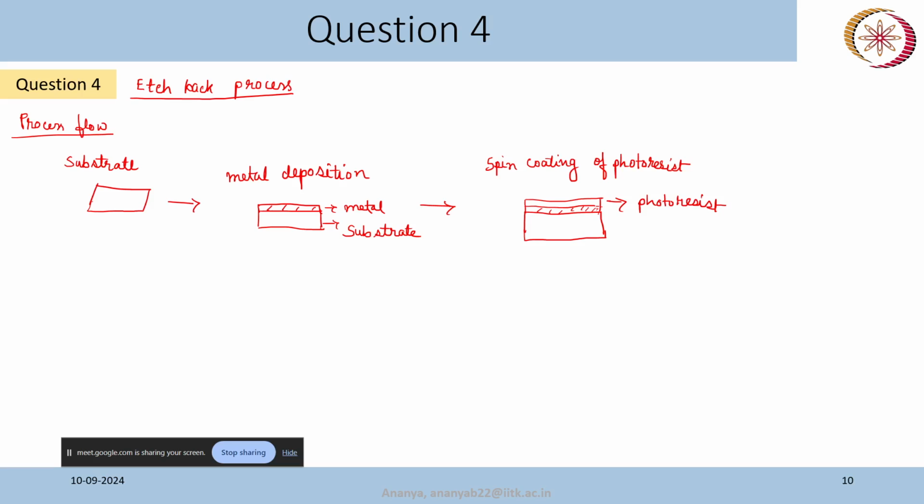So those parameters, the exposure time, development time and the thickness of the photoresist, have to be optimized before doing it on the actual device or your final substrate.